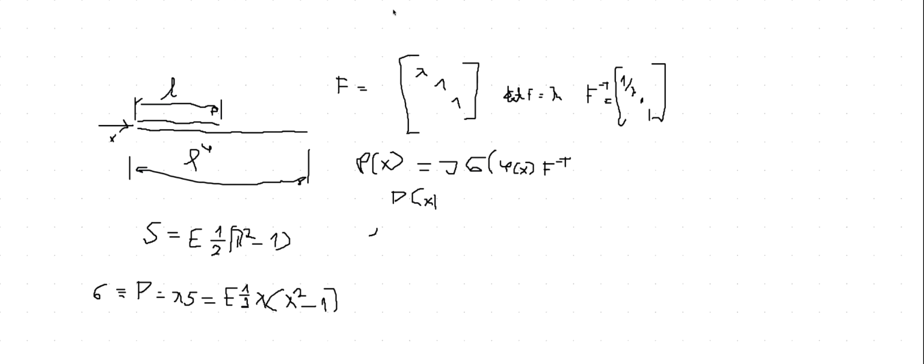So basically, the idea is, if I have that, I can take into account what happens when lambda goes down to 1. That means there should be no deformation. I get that my true stress, sigma, should go down to 0, as it should, because Hooke's law is correct. Then if I have a very large stretch, I'm extending the bar 10, 100 times, let's say going here to infinity.